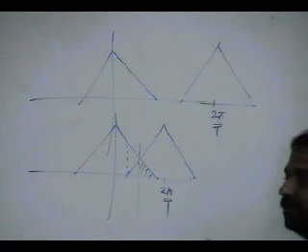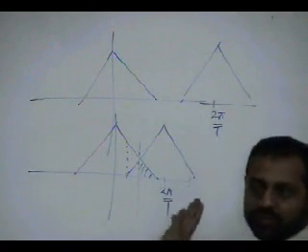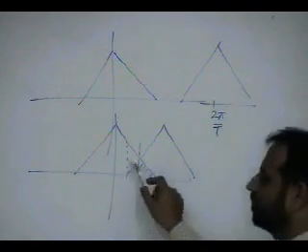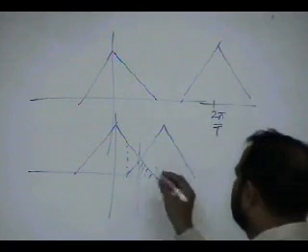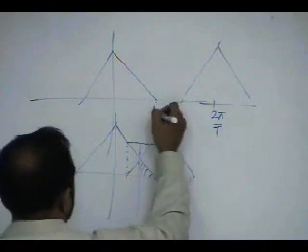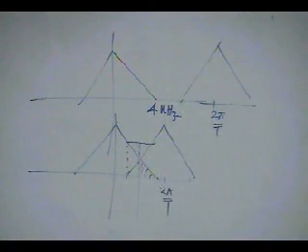So it is better that if you are sampling slower, you first throw away this part using an analog filter. Throw this away and then sample at a lower rate, so that at least you don't corrupt this part. So what you get here is this. For example, if the highest frequency content is 4 kilohertz and you sample at 4 kilohertz, what will happen?